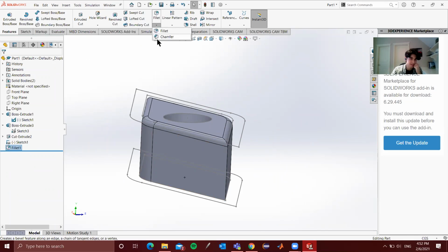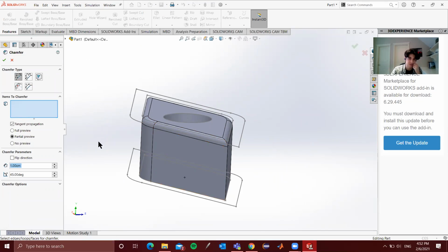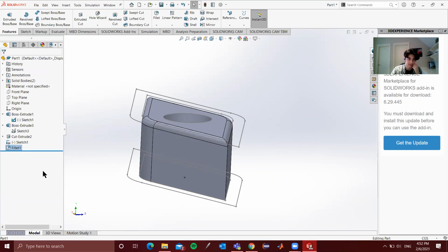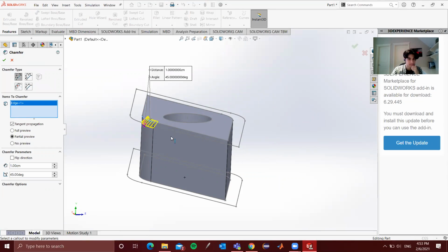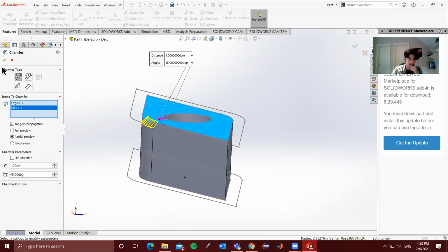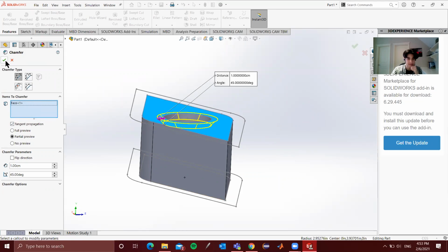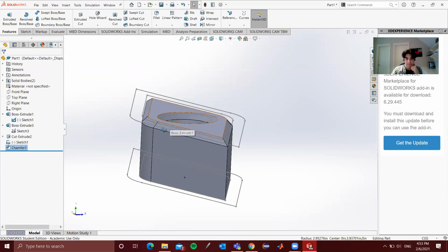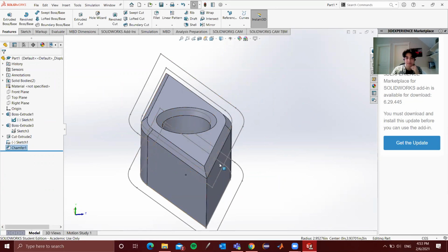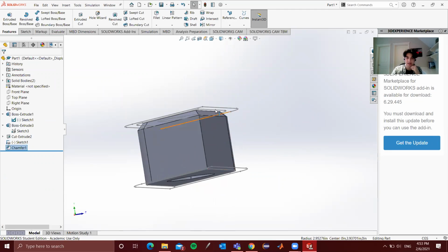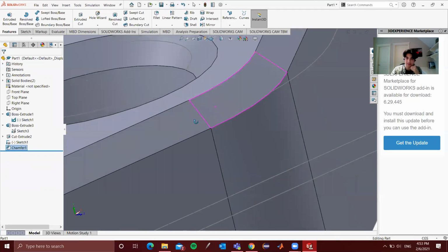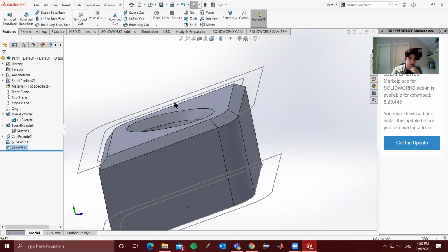And the opposite of that would be a chamfer. So essentially, instead of having rounded edges, you can essentially get rid of your fillets. So if I delete those, and if I round them out, and go all around, but you can actually just click the face and it'll do the same thing. So if I get rid of this, you'll notice it took every type of contour around there and it created a slant, or a diagonal type of face here. So it's not necessarily round.